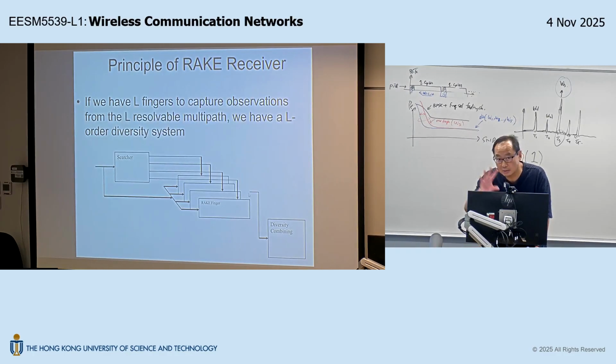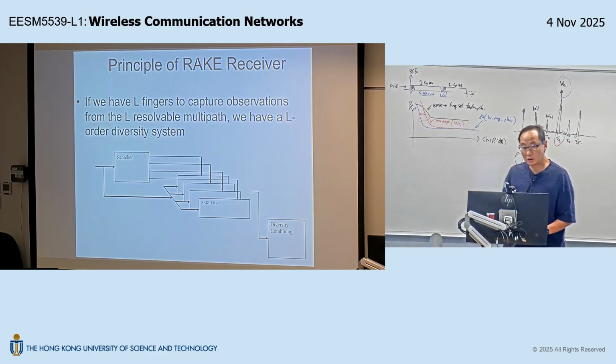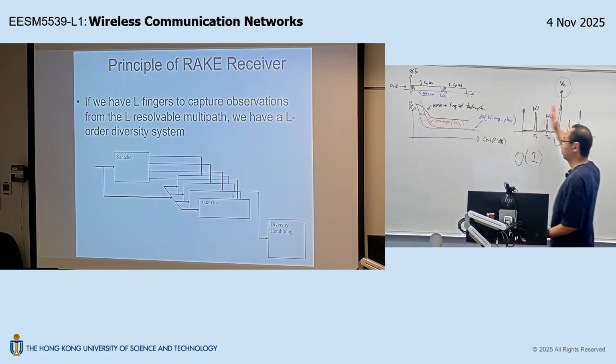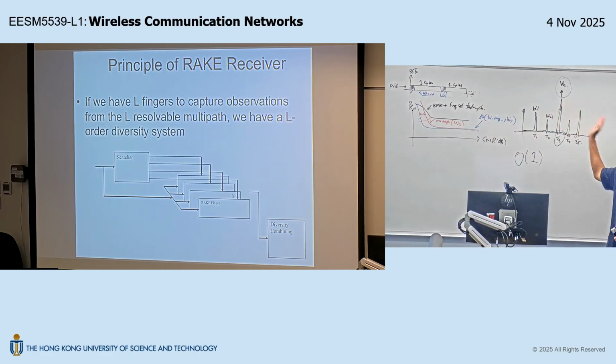So, okay, that's the same idea as the Wi-Fi chipset case study. Okay, so in practice, in the CDMA mobile, we usually have 4 despreading fingers. Okay, and with 4 despreading fingers, you can also use that to support any number of resolvable paths.